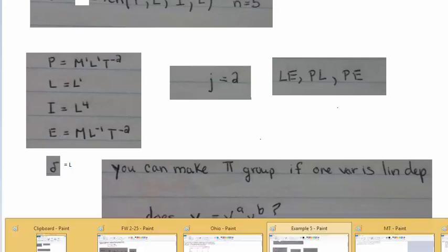So here we're good. You just solve the rest of the problem the way we solve the other 2, except you'd use the grouping here. Now, also note that the grouping you choose is not necessarily unique. In other words, you could choose this grouping, or this grouping, and you could get a solution to the problem. So the solution that you get to the problem when you're using the Buckingham pi theorem is not always unique. Okay, let's do another sort of tricky example.